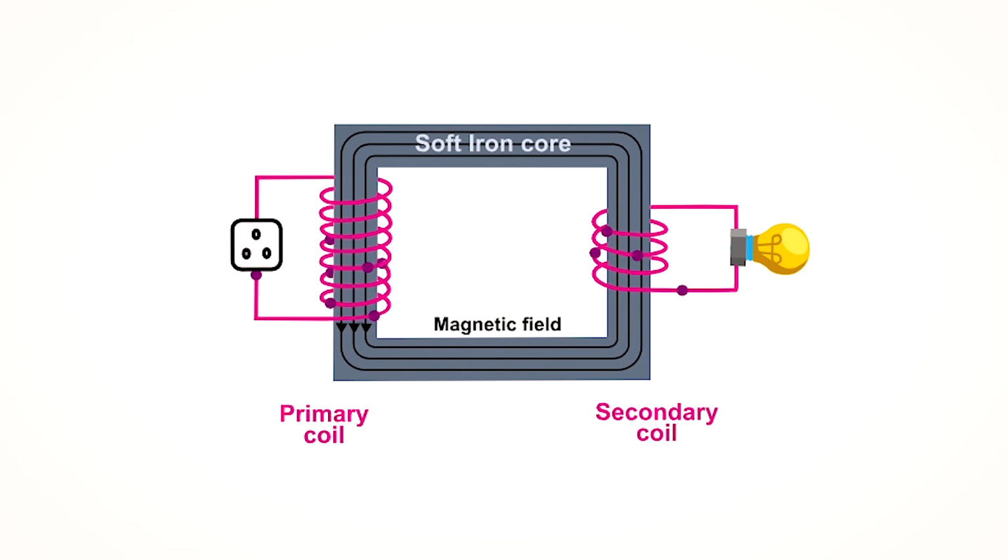When you add a core material like ferrite or laminated silicon steel inside the coil, the inductance increases because the magnetic permeability improves, allowing stronger magnetic flux for the same current. But there is also a limit. If too much current flows, the core saturates, and the inductance suddenly drops, which can damage circuits.